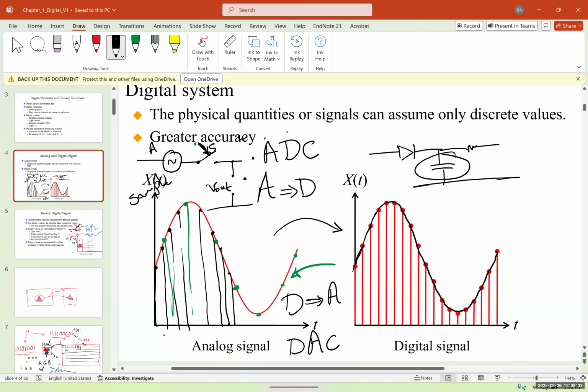You can use a simple capacitor to do it, and we call it an envelope detector because it creates an envelope over the signal. Okay, and this detector is actually the principle of AM, what we call amplitude modulation. Next semester, if you take a communication systems course, you're going to learn about AM and FM, which are amplitude modulation and frequency modulation.